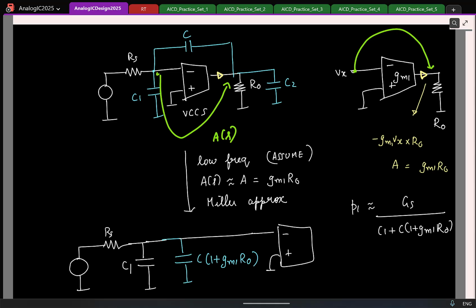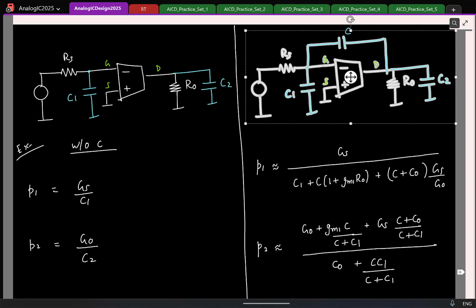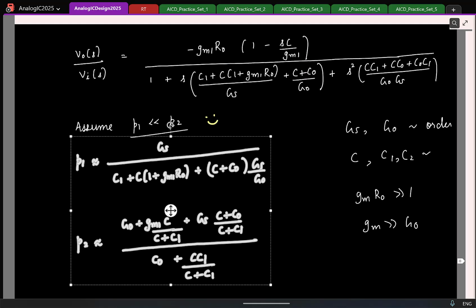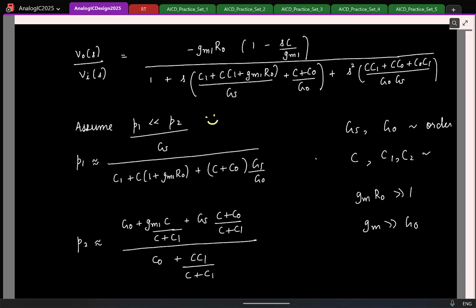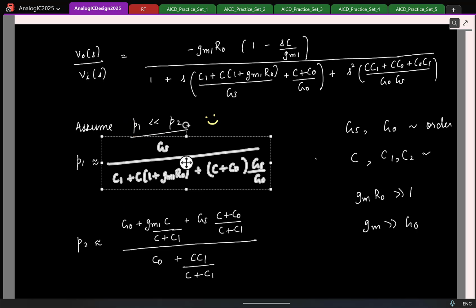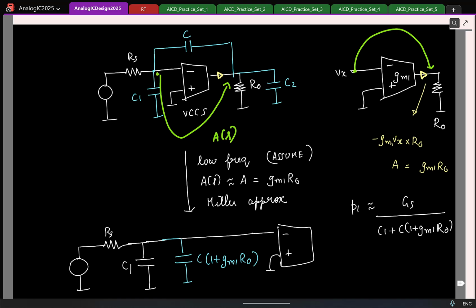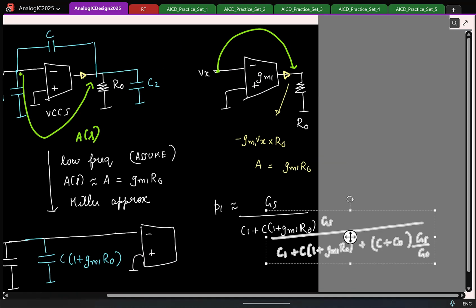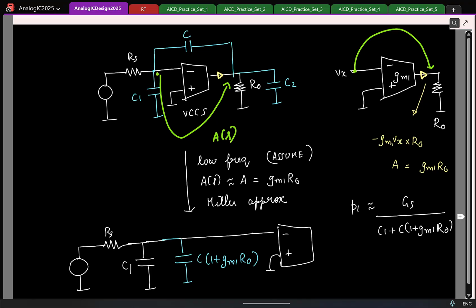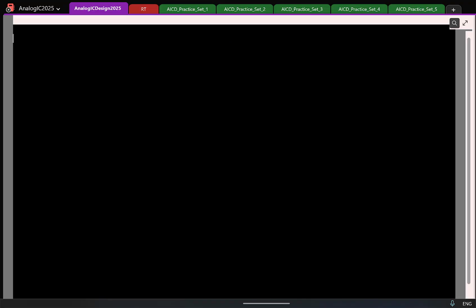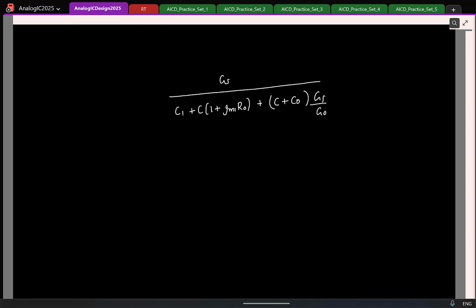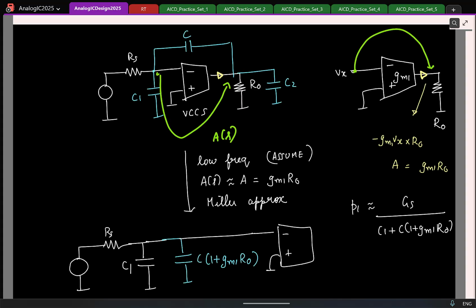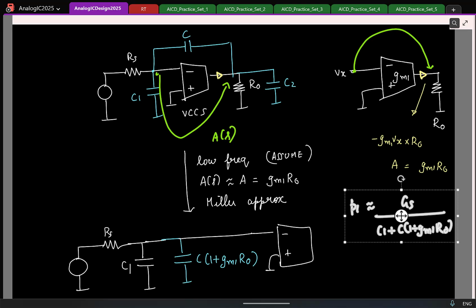And again, remember, the assumption we made was this is a low frequency pole, and we can check it. In fact, we saw that pole 1 was a low frequency pole. Right? We saw this was actually much smaller than P2, so this is a low frequency pole. So let me actually copy the expression we got from solving the equation. This is the expression I got from approximately solving the quadratic polynomial, and intuitively this is what we guess as the pole location.